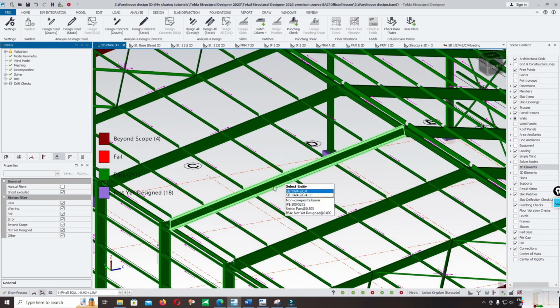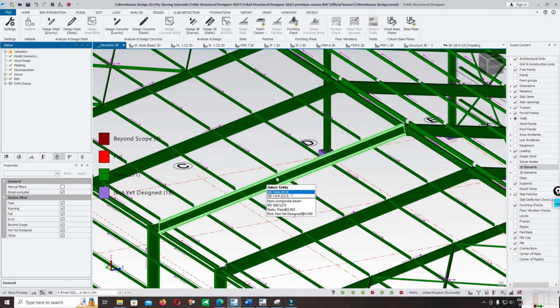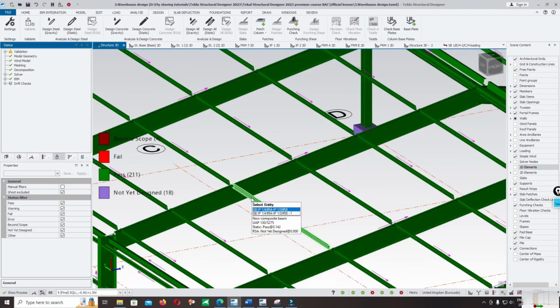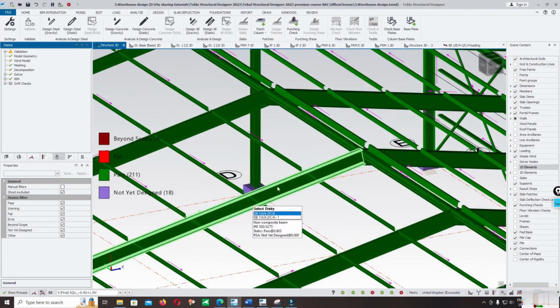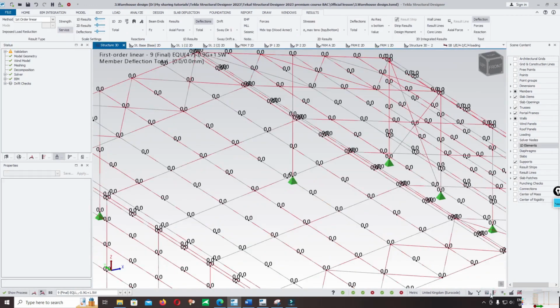For the location in the compression plane, it doesn't matter whether to add the torsional restraint, but on the other side, for the tension plane, we must add it again. You can check it in the analysis result for more detail.